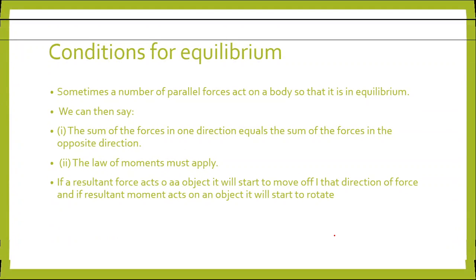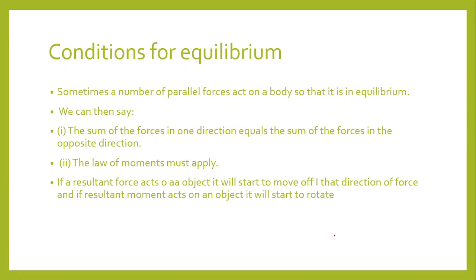So I'll just read it again. Sometimes a number of parallel forces act on a body so that it is in equilibrium. We can say that the sum of forces in one direction equals the sum of forces in the opposite direction. The law of moments must apply. If a resultant force acts on an object, it will start to move off in the direction of the force, and if a resultant moment acts on an object, it will start to rotate.